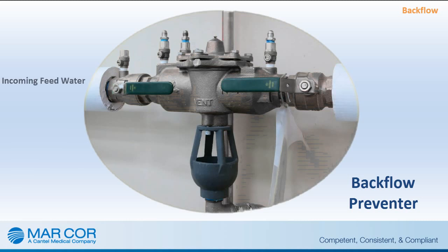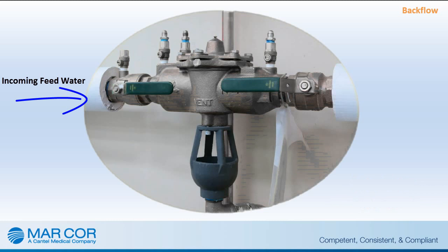The backflow preventer is a check valve on the incoming feed water that prevents pretreated water and disinfectants from backing up into the municipal water supply. The backflow preventer is required by many municipalities, but is not required in all states. Testing and monitoring requirements are determined by local codes and authorities and is typically done annually by an outside vendor.